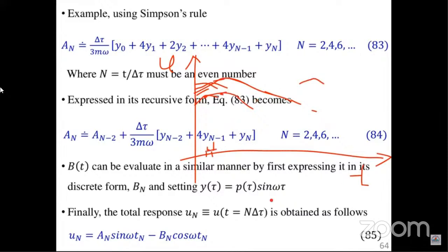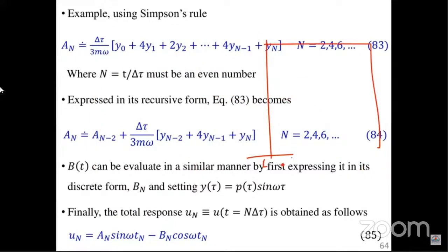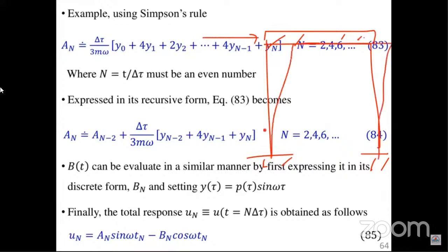Now, something to mention is that the approach that we are using can only be applied to linear systems. A linear system, let's consider our steel column. If we have a rigid portal frame, or a frame, carrying a platform there, then we have an impact loading there. It could be a bomb blast, acting over a short time. So our structure will deform, and then you shall have a to and fro motion, which will continue dying due to damping.